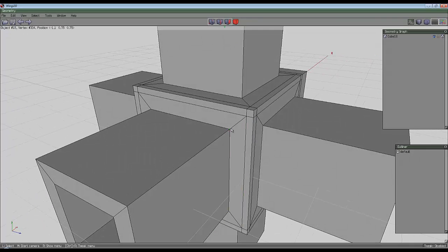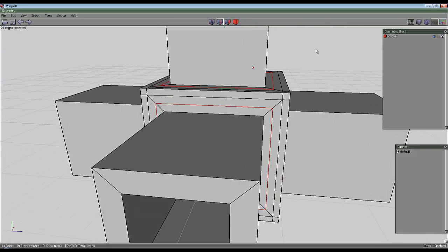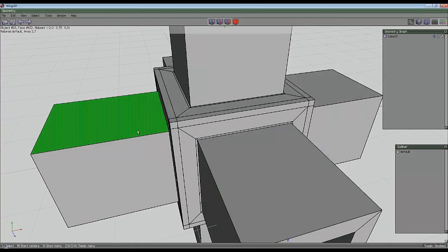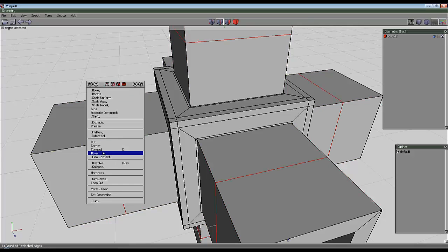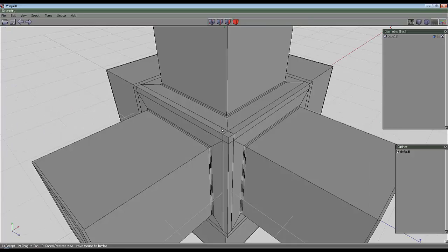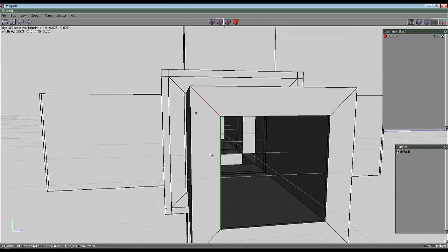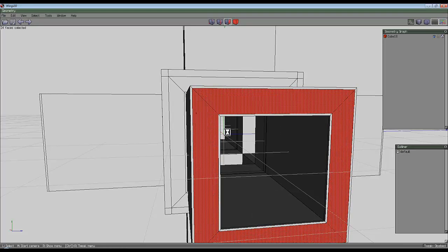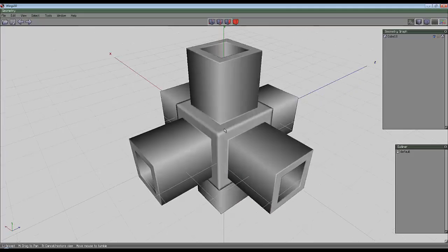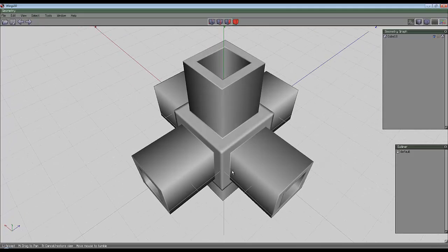So to do that, I'll do what I did before, use I for identical and then C to connect those, and if I do scale uniform, I can bring those in closer to that edge, and then I for identical there, C to connect and bevel, and that'll put some there, and then here, so go I for identical, C to connect and bevel, and put some in there, hit the tab key. Okay, so it's getting close.